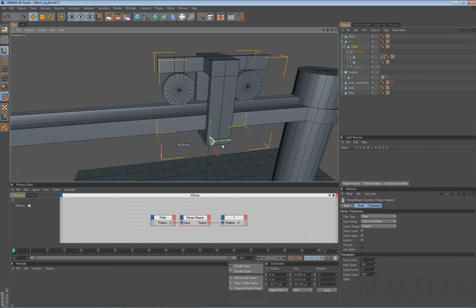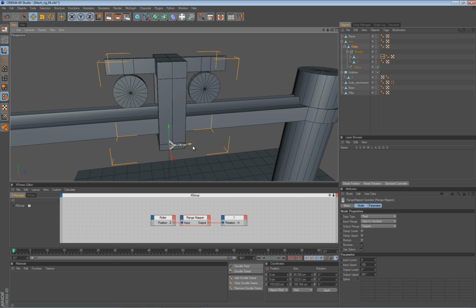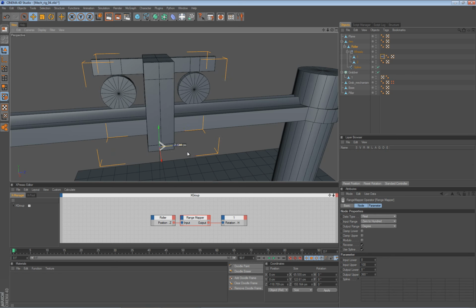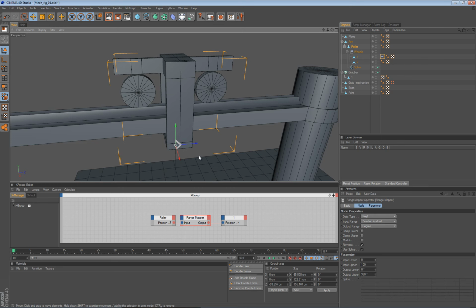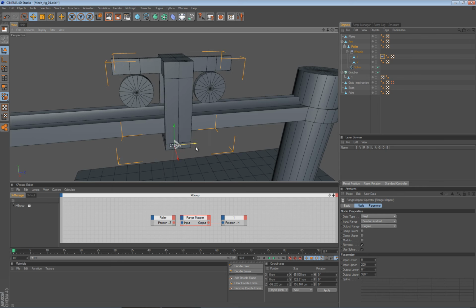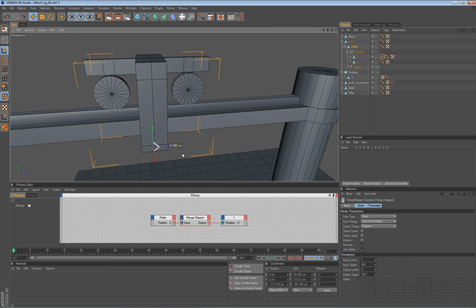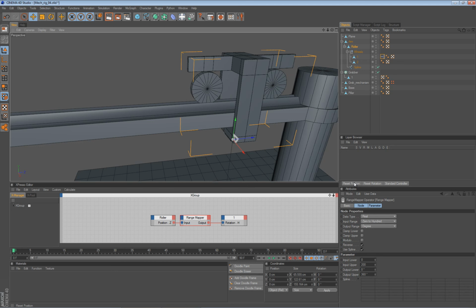And actually it seems good, but the rotation is not quite what we should expect. You can see it's almost like the wheel is sliding, and we can actually rectify this by increasing this value. So let's try 200, for example, and see what happens. And this feels a lot more natural to me. Okay, so we can reset the position. You can see that is really useful.